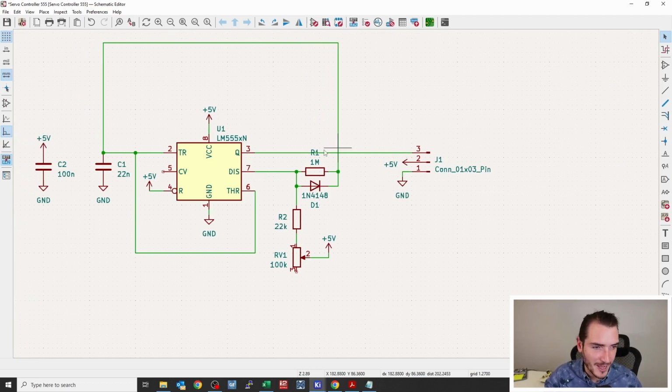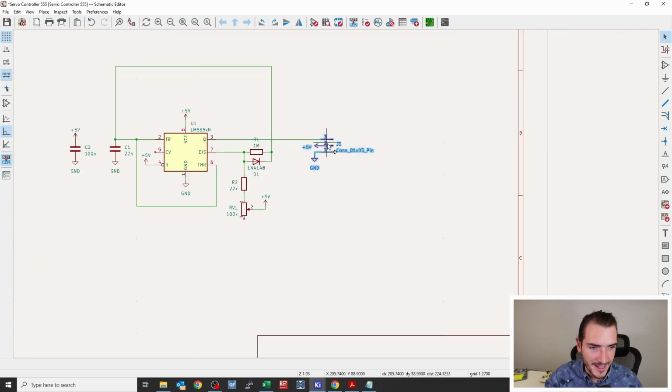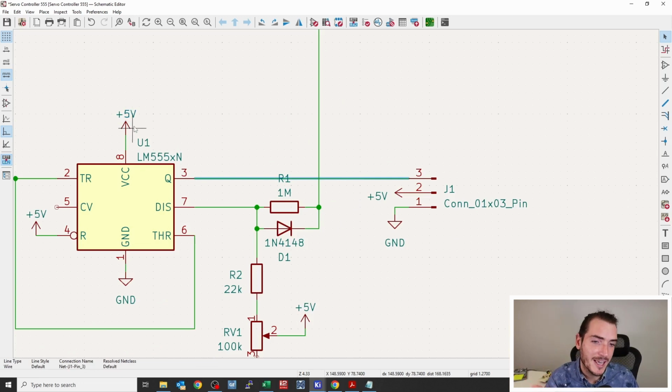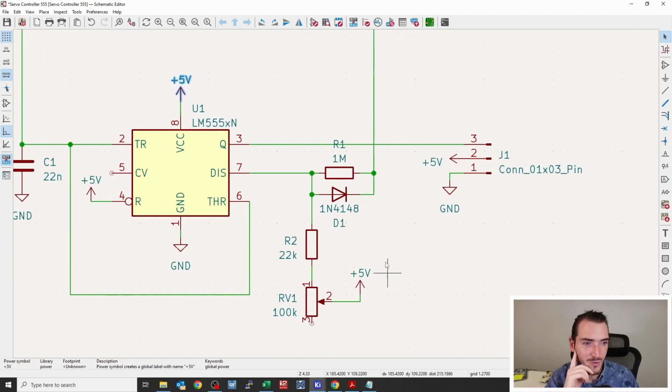And we have this wire crossing over our schematic here, and it also means that our connector is kind of tethered spatially to where our circuit is. Maybe we don't want that. Much like how we use these power labels to join 2 parts of the schematic without wires, we can use a net label, where a net is just a connection. Everything that's connected together is on the same net.